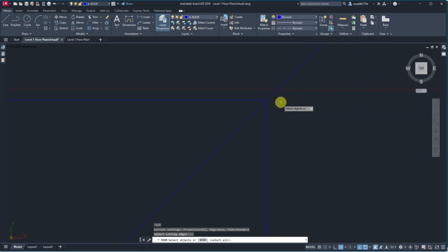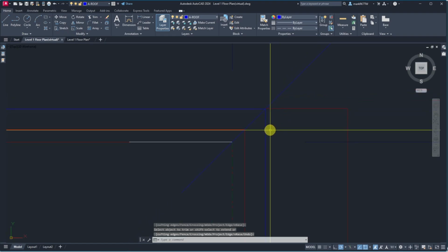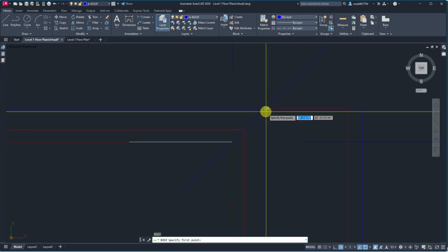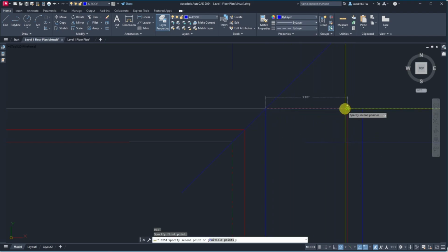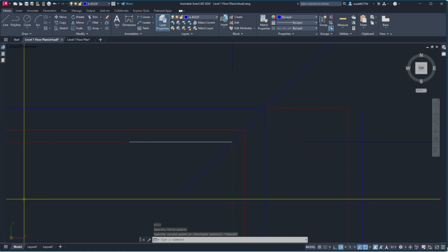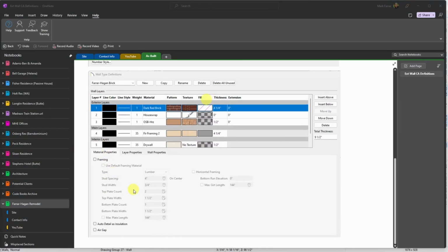Now, what I'm going to do is trim to here because I've got to figure out what my distance is here, because this should be 4. And I have a feeling it's going to fall just, now that's weird. Maybe it's only 3. 3 3/8. So I must have measured 3 3/8. So how I can check that is go to my drawing and see what I've got. So for here, I've got a 4 1/4 brick over the 1/2 inch.